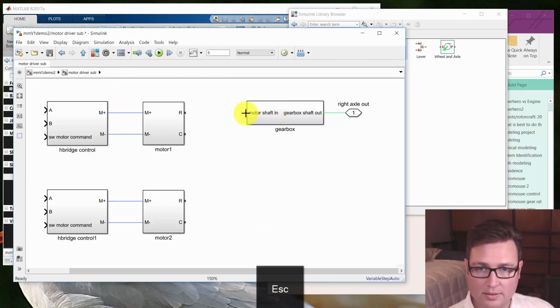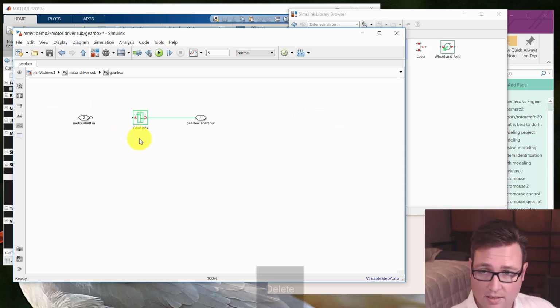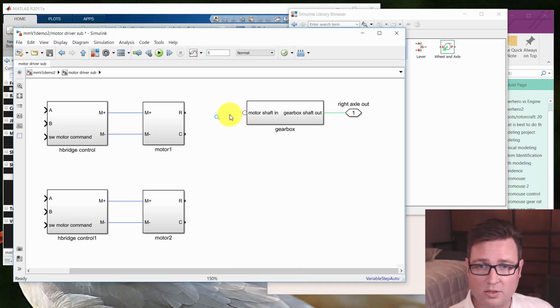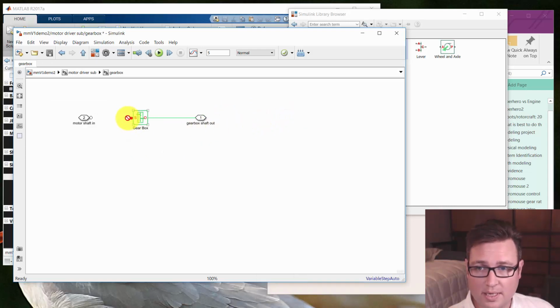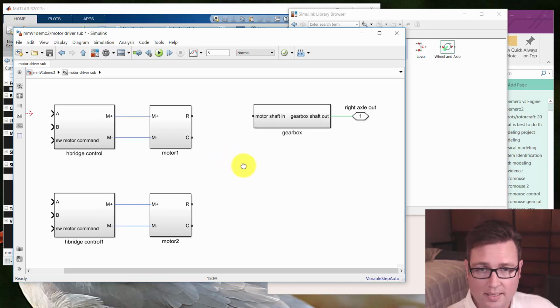And you'll notice it changed to the right kind of a node there. Now Simscape and Simulink can understand, okay, that's just the domain. Let me unhook it and show you what I mean. If I unhook that, it knows it's a physical port, but it doesn't know what kind. So as soon as I hook it up, then okay, that's something it knows how to deal with. Okay, very good. So we've got that.